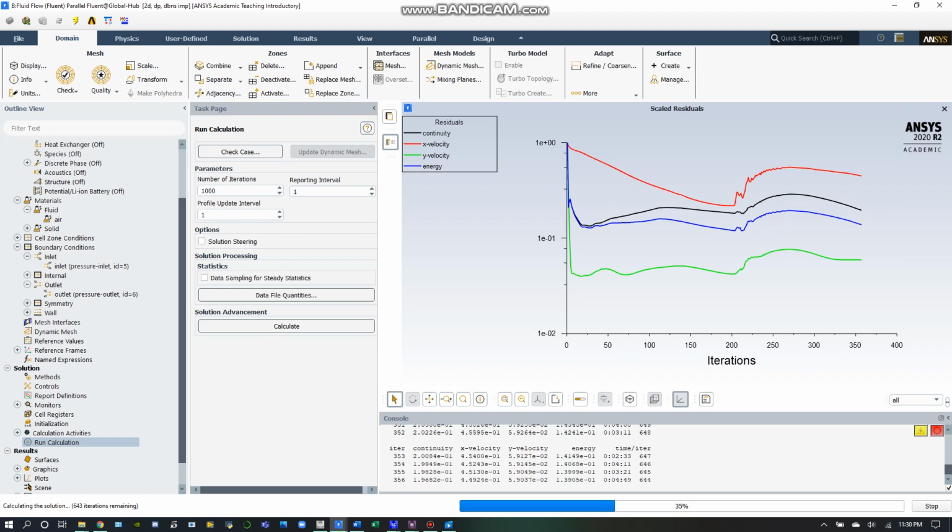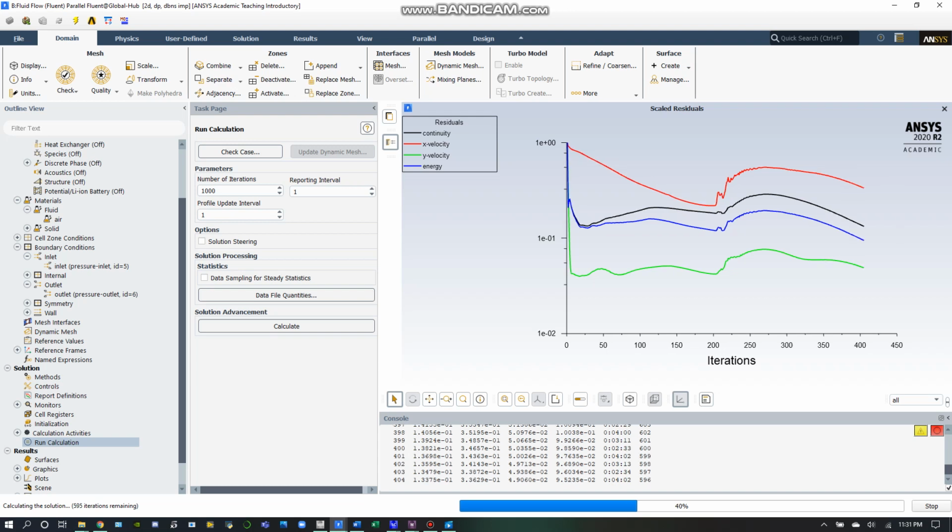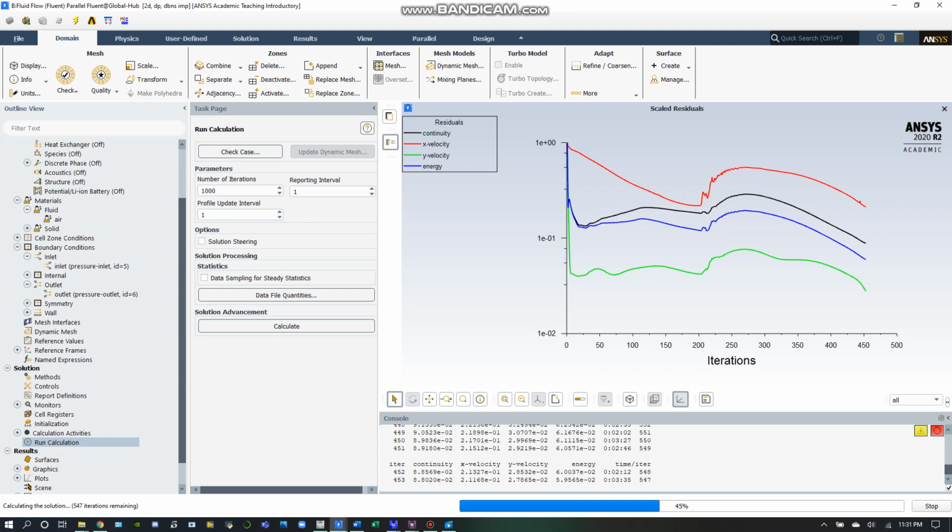Now it's interesting to think about whether your results will be the same as the bell nozzle, because the expansion ratio is the same, and we set the same pressure for the inlet and temperature as well as for the exit. However, we will find out that our values are not actually the same, and we find out that our bell nozzle exit Mach number is actually higher than our conical nozzle exit Mach number, which is actually a desirable result, and more of that will be discussed in my results.